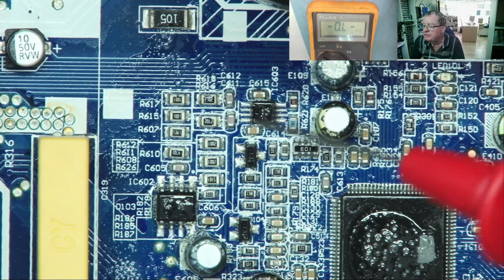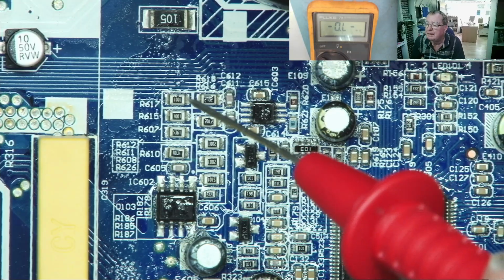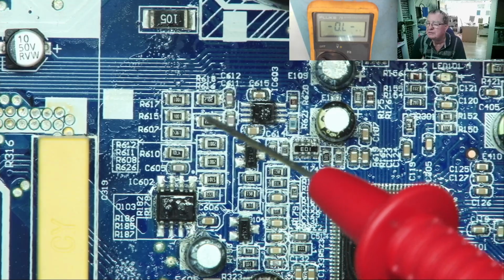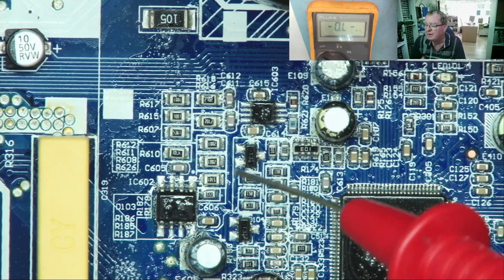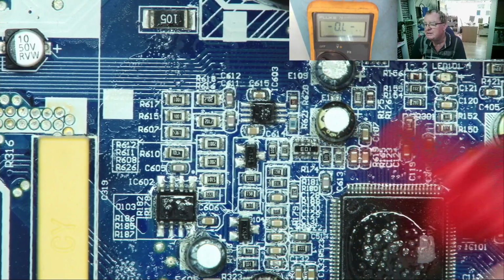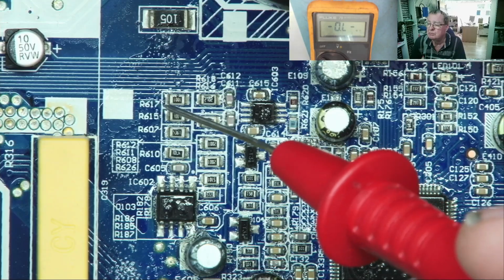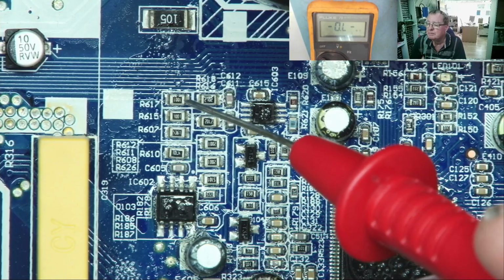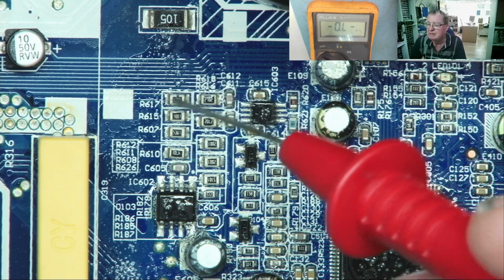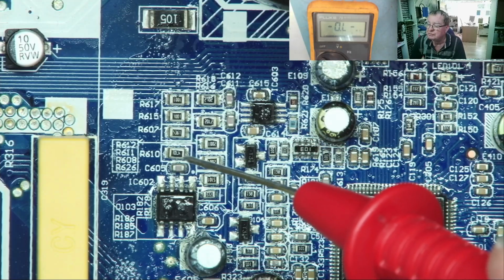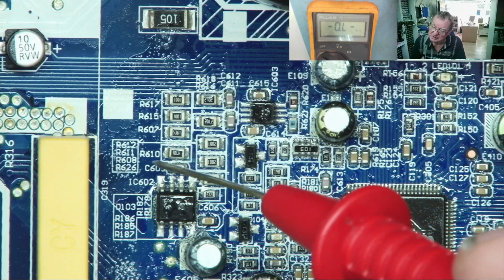So for example, we see some resistors on this board here, and we see various markings. Now, it's important to learn these marking systems, because otherwise, when faced with a board like this, you would have to go and look up every single resistor to see what the markings are. For example, that is not a 1001 ohm resistor. It's 100, and the last digit is how many zeros? 1 more 0, so that's 1000 ohm. This one actually here is 470 and 1 more 0, so 4700.